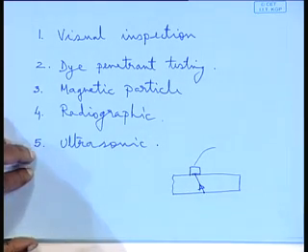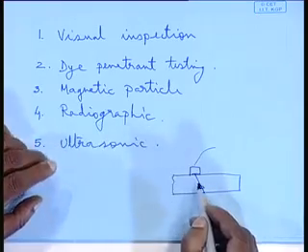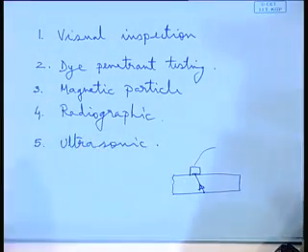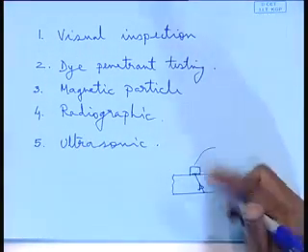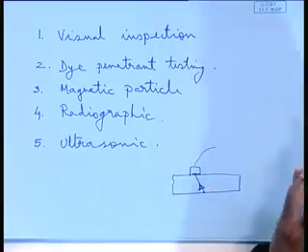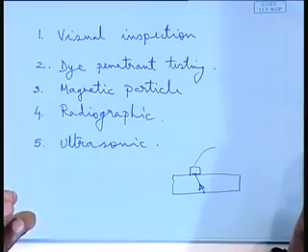That is the principle, and even these probes can be used as a thickness gauge. These are small probes which can be held just by the fingers. So, it is more portable, you can take it anywhere, into a nook and corner, or wherever a complicated structural geometry is there.